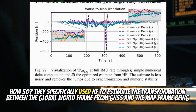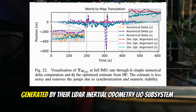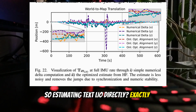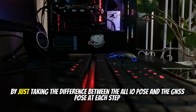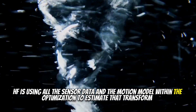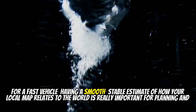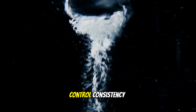They specifically used HF to estimate the transformation between the global world frame from GNSS and the map frame being generated by their LiDAR inertial odometry, LIO, subsystem. So estimating that transform directly. Exactly. And the transformation sequence they got out of HF was significantly smoother and less noisy compared to trying to calculate that same transformation manually, like by just taking the difference between the LIO pose and the GNSS pose at each step. Which makes sense. HF is using all the sensor data and the motion model within the optimization to estimate that transform. Right. For a fast vehicle, having a smooth, stable estimate of how your local map relates to the world is really important for planning and control consistency.